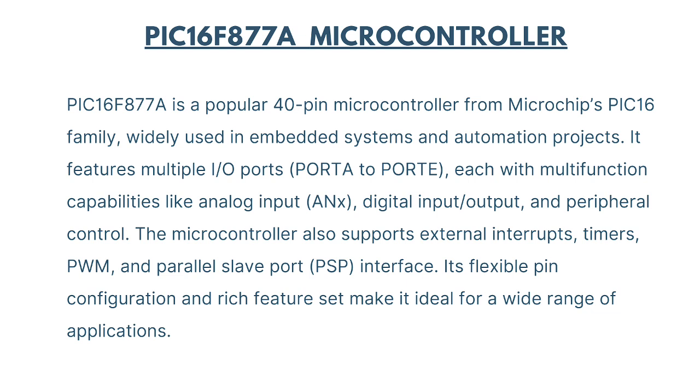Moving on, we are going to discuss the PIC16F877A microcontroller. PIC16F877A is a popular 40-pin microcontroller from Microchip's PIC16 family. It is widely used in embedded systems and automation projects. It features multiple input-outputs from port A to port E, each with multifunction capabilities like analog input, digital input-outputs, and peripheral control. The microcontroller also supports external interrupts, timers, PWM, and the parallel slave port, that is PSP interface. Its flexible pin configuration and rich feature set make it ideal for a wide range of applications.